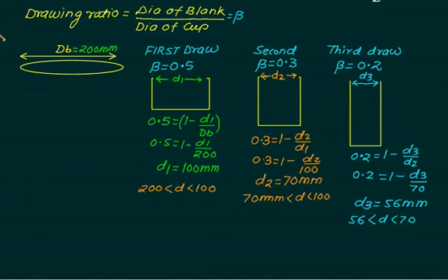In a deep drawing, this surface, that is this part and this part, this section, you have to always make rounded like this. If you make sharp edges, a wrinkling effect will be there because the plate suddenly changes its structure. This one is tensile force, this one is tensile force and this will be compressive force. So it will try to break here. So cracking is very common at the bottom edge.